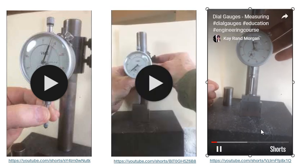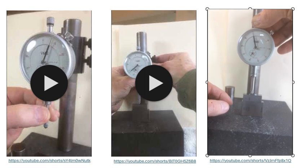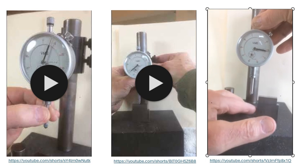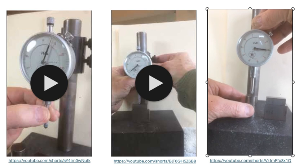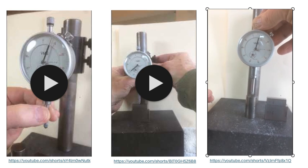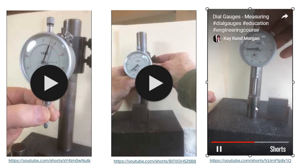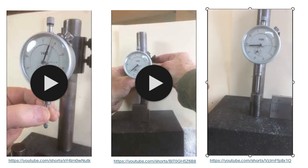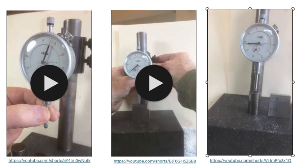Then we come into the measurement. After adjusting the 0, we do the measurement. We will push this gauge block out, and we're going to bring our dial right there because we want to measure the height of that. And then again, we push this little contact to the surface. And here is your reading.